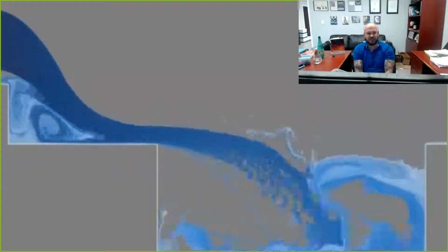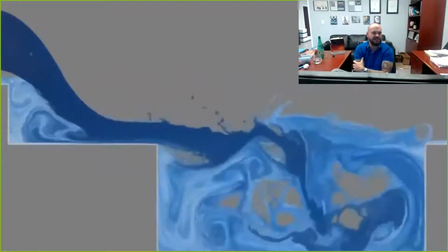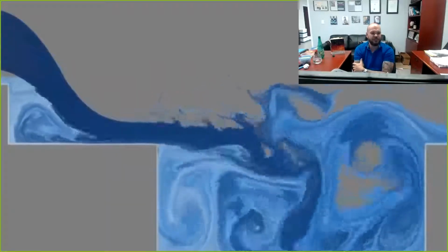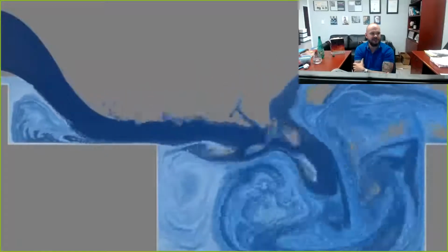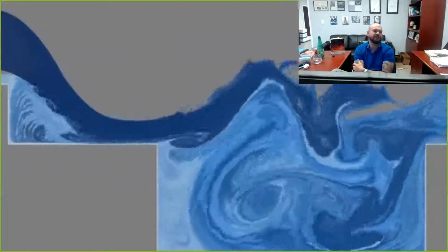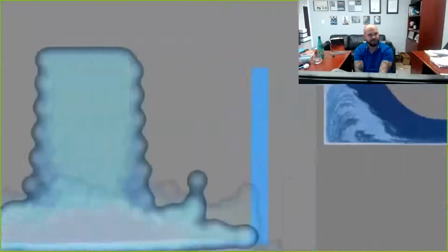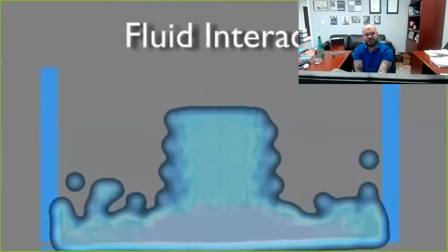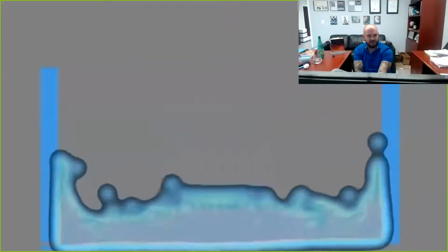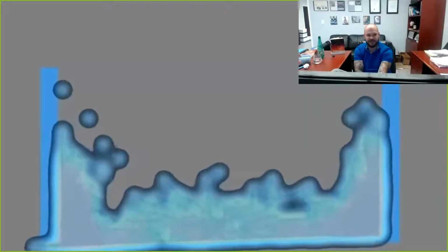Now here are some examples of fluid flow practices that take place inside all castings made by traditional means. Anytime your metal has an opportunity to drop within your casting cavity, it looks like this, right? So if you're gating at the parting line, it falls. Anytime your metal falls within the casting cavity, it's doing this kind of thing, where blue is the metal and every other color is a combination of metal and air. Every separation and recombination of a droplet, you're loading in oxide films and introducing pre-existing cracks into your melt.